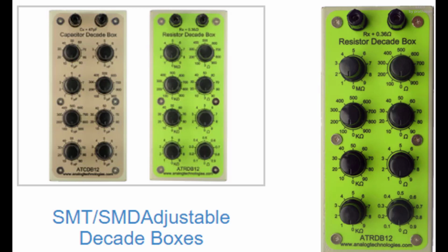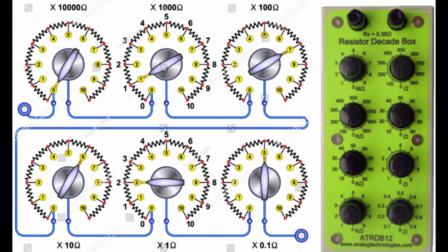All types offer a convenient way of selecting and quickly changing a resistance in laboratory, experimental and development work without needing to attach resistors one by one, or even stock each value. The range of resistance provided, the maximum resolution, and the accuracy characterize the box. For example, one box offers resistances from 0 to 100 megohms, maximum resolution 0.1 ohm, accuracy 0.1%.